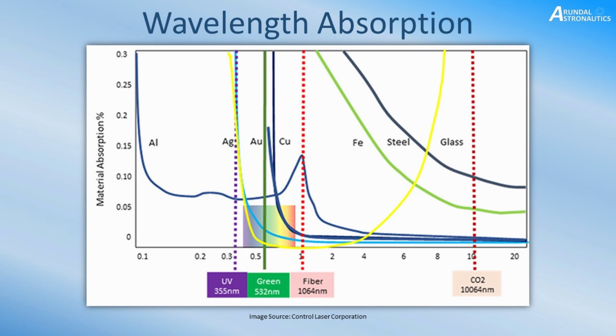If we were therefore to consider laser welding or cutting with aluminium, we would want to pick a laser that's either in the low wavelength band or around the 1000 nanometer band for optimal performance. The important lesson here then is that the wavelength absorption of a material should match the laser output that you're after, because otherwise the energy won't be absorbed properly by the material and therefore the heating won't occur as rapidly or perhaps even at all.